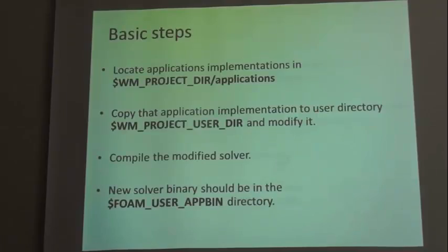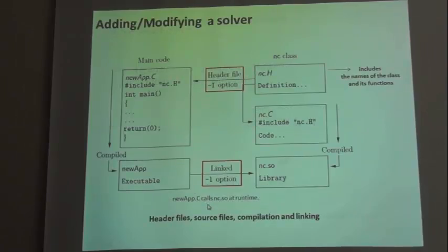Coming to solver development, the basic steps in modifying any of the existing solvers is that you create a copy of the actual application that you are targeting. In this case it's interFoam, so you copy all the source code and other files associated with it to your local directory, and you modify the solver, and once you compile it, the executables will be available in the user directory.